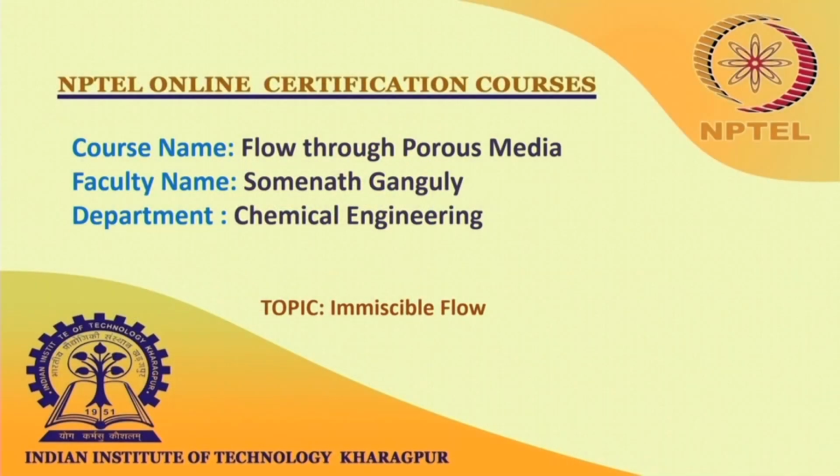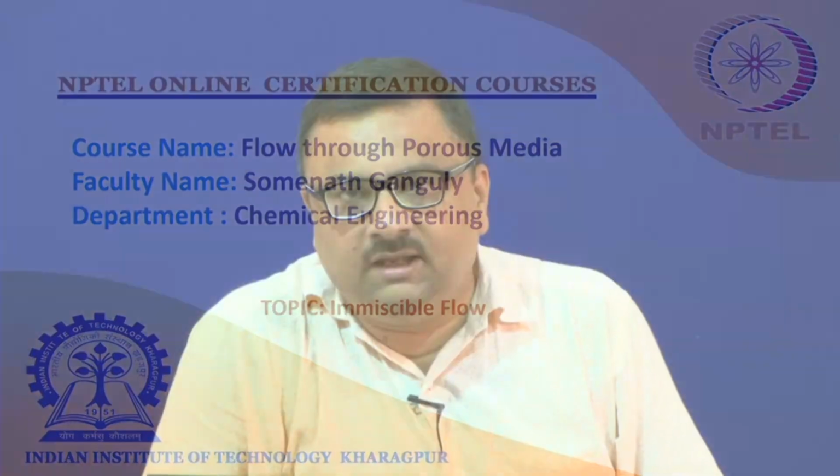I welcome you to this lecture of flow through porous media. We were discussing immiscible flow. In particular, we briefly introduced this Buckley-Leverett formulation, where the porous medium is at interstitial saturation, and then the wetting phase would be injected into that porous medium, and we want to study how saturation changes, how the wetting and non-wetting phases come out, how they are collected, and at what rate they come out at the effluent.